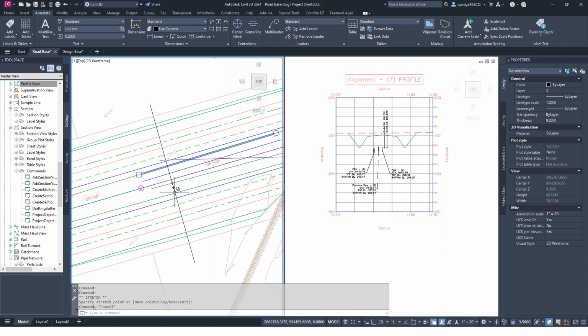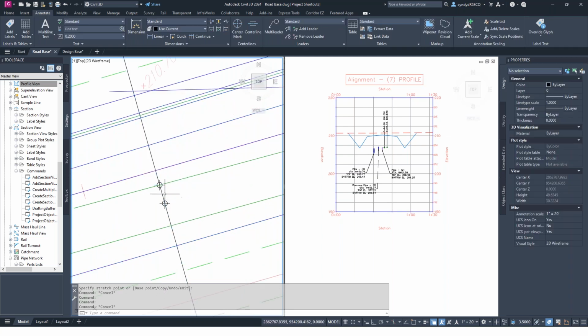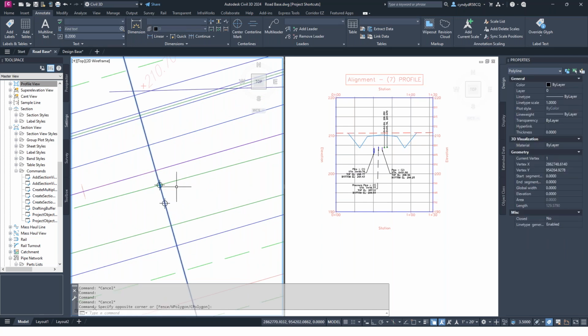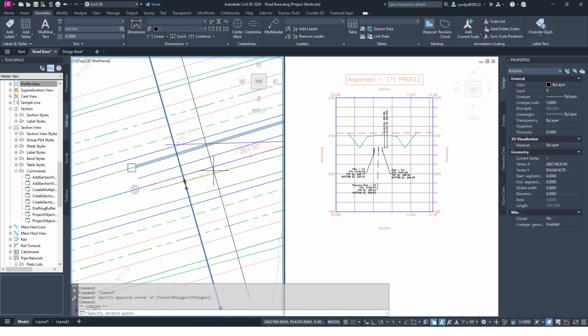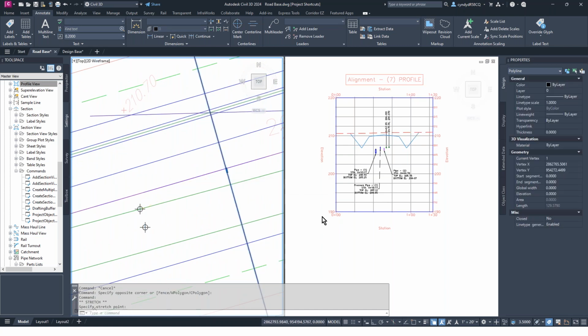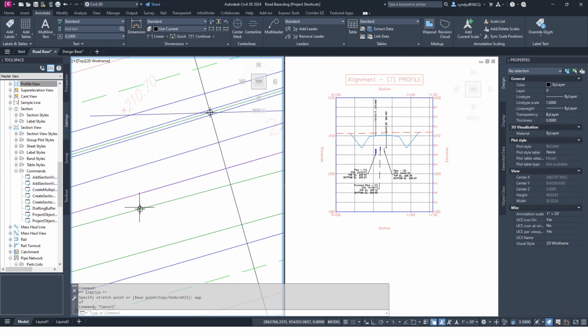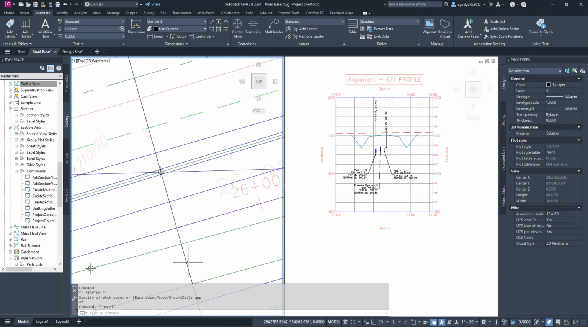And you want to know, okay, well, what's the conflict going to be? What if I check it out and see what's happening? If I can just grab my polyline there. There it is. And see what is happening and just make sure it crosses the crossing right here. And you see that updated there, but of course I need to move this point over to this new location here and use my apparent OSNAP. Then of course I can move this one too, but it's not the point I'm concerned with.